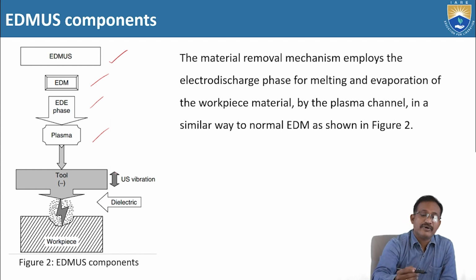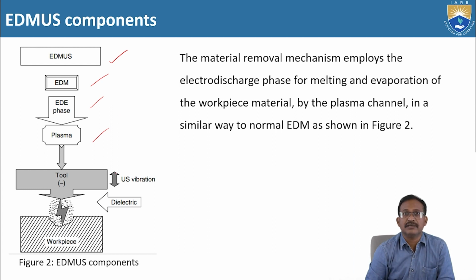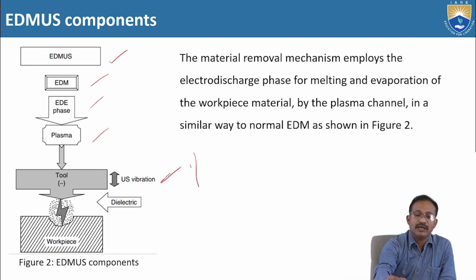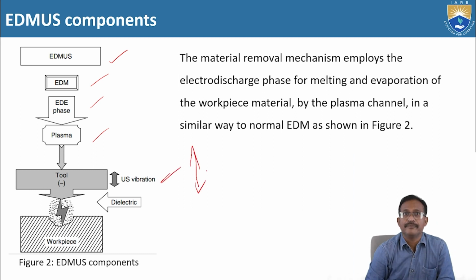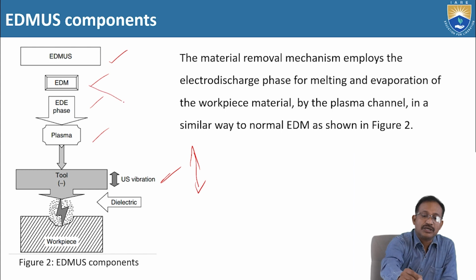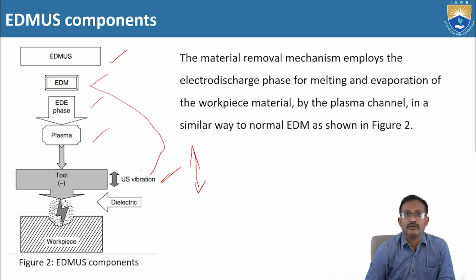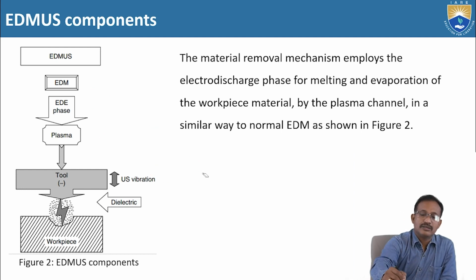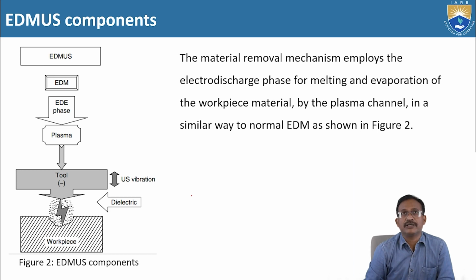Here for the tool we are setting the ultrasonic vibration. The ultrasonic vibration is attached to the tool already equipped with the electro discharge machine. However, the dielectric fluid medium is flowing or circulating between the tool and the workpiece, where the spark generates. So this is the component of EDMUS, electro discharge machining ultrasonic.